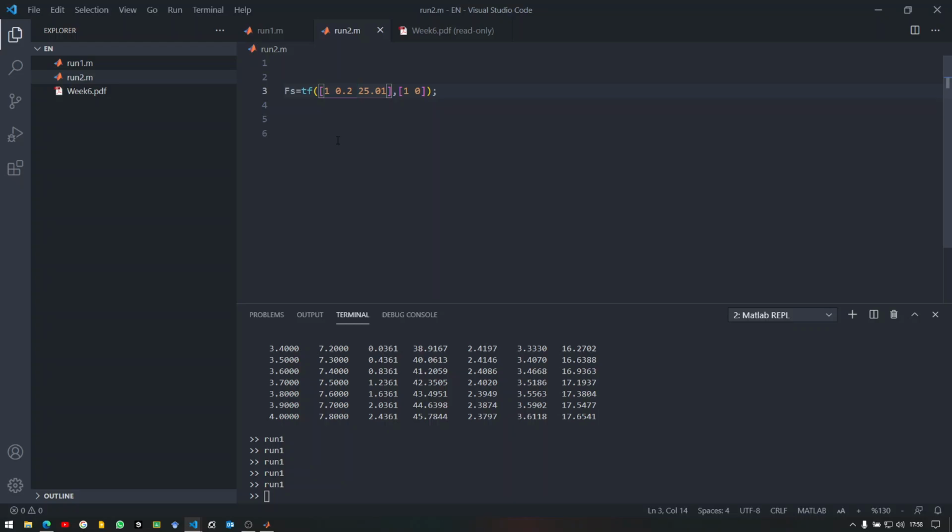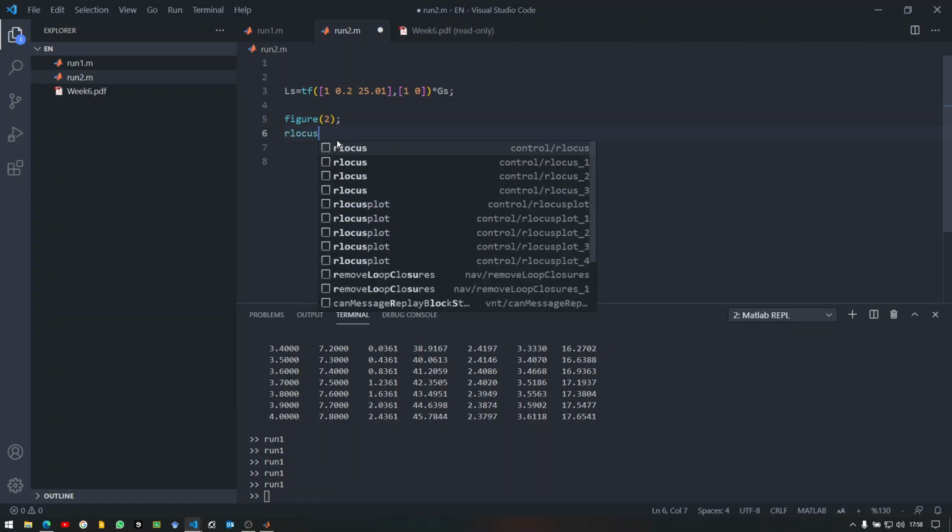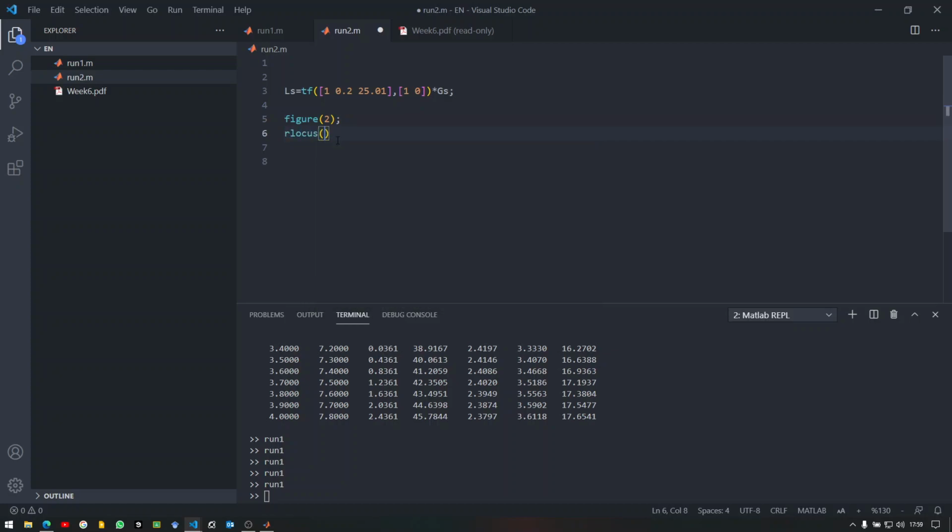I have to cancel them both at once. So this would be then the controller that I will be using. And let's look at the loop transfer function here, and the root locus of the given loop transfer function. Because I can use this to come up with a gain, because that's the only missing part here. And then I would get a controller.